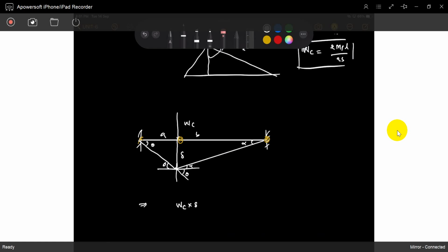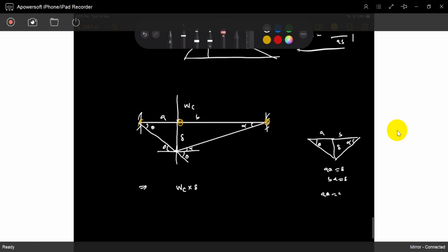So previously what we discussed, same thing again. This is alpha, this is theta, this is AB. A theta is delta, B alpha is delta, we already wrote. So A theta is equal to B alpha. So alpha is A theta by B, you can write it. So what is the internal work done? Internal work done is this has a plastic hinge MP into theta into alpha.